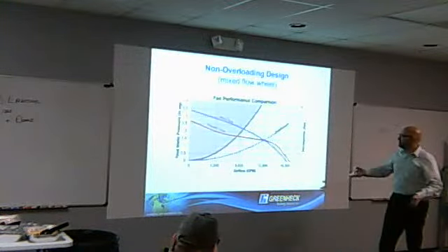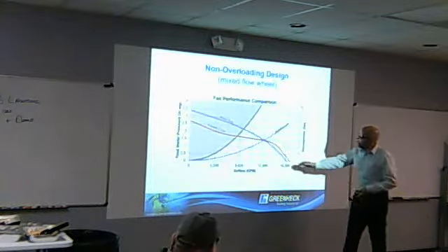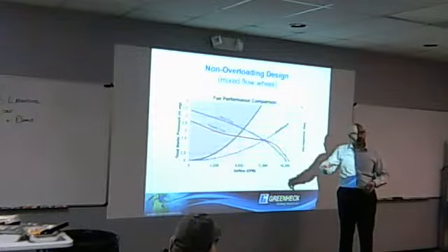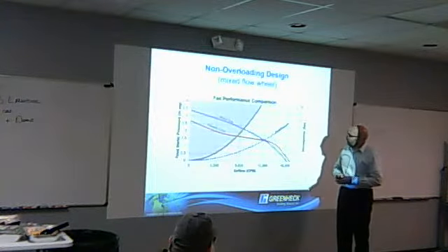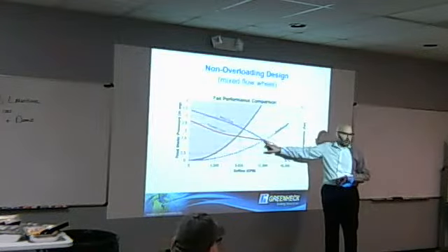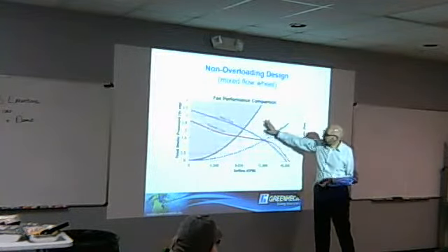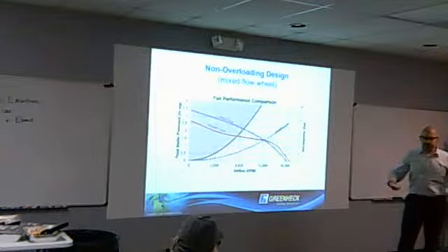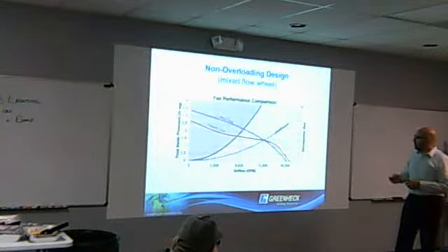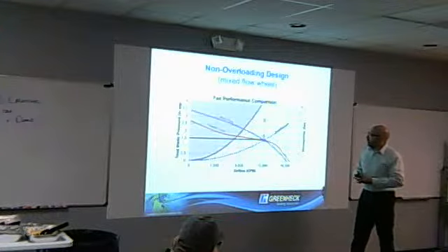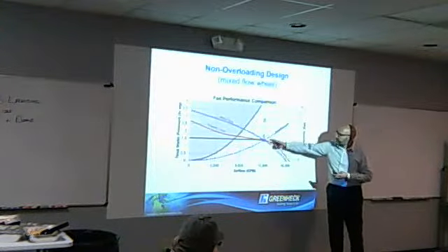So this is a system that's installed, and let's say that system was requiring 12,000 CFM against 1.5 inches of static pressure. That intersection of the RPM and the system is your operating point. These dashed lines are the brake horsepower curves of the fan system. So if we pick a point on there as our operating point, and we want to read to our brake horsepower, we read up to these curves.